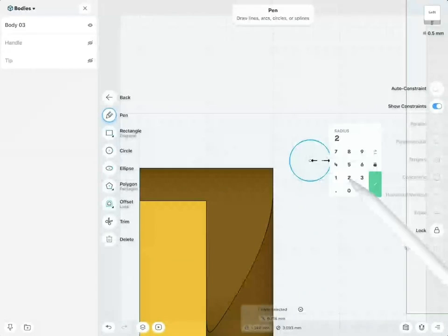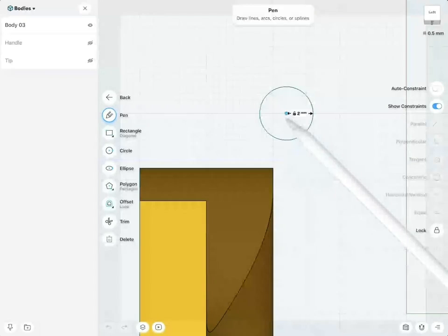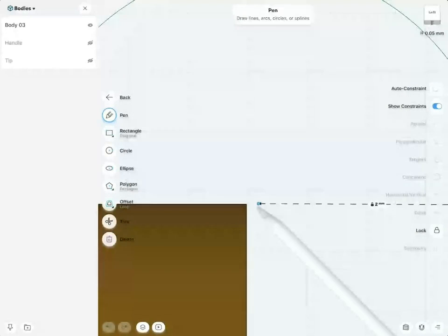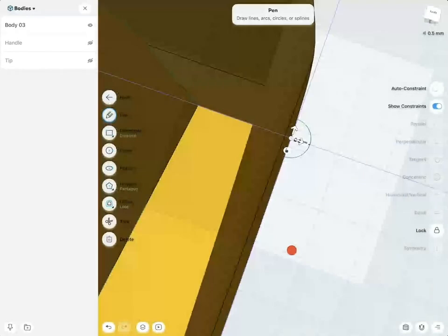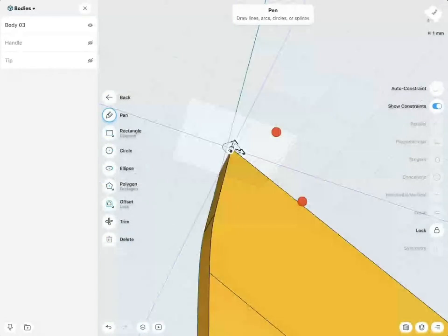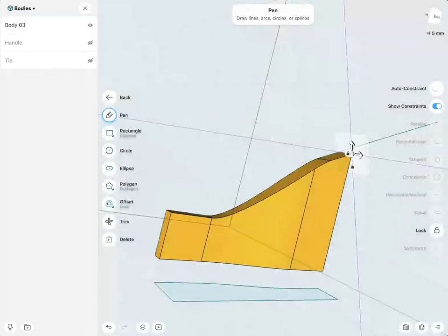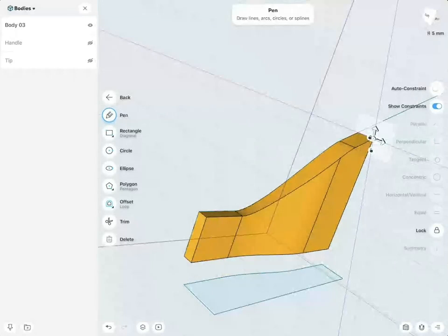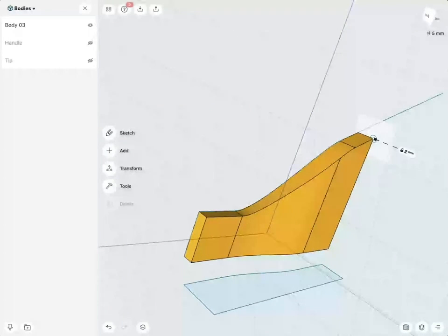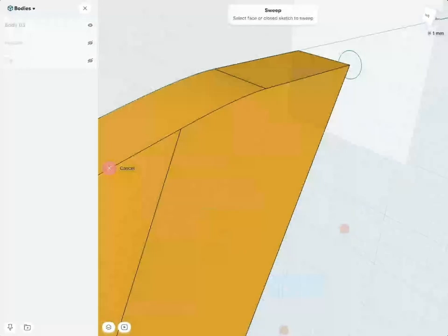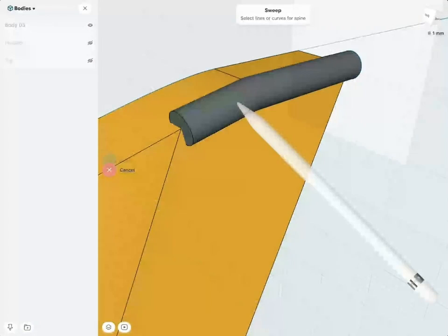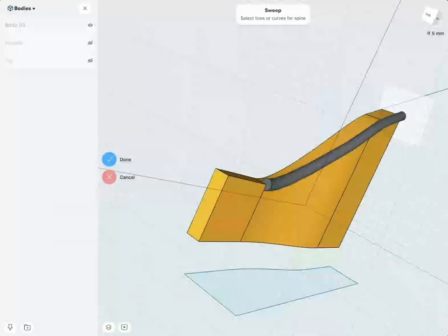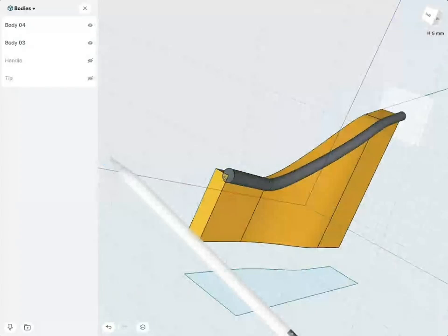We can specify how thick this wire should be, and then this midpoint I can move around and position it to this corner. I don't have to be super precise, because you know from the first piping exercise with the 3 pipes, we can have an offset, and with the offset, well, we pipe along the edge with an offset. Very good. Then we can go back to tools and sweep this along this edge and this edge. There. Very nice.